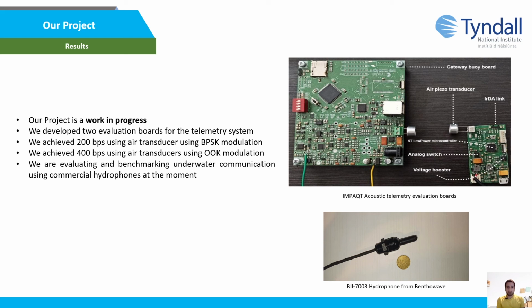So far, we were able to communicate at 200 bits per second using air transducers with binary phase shift keying modulation, and also we were able to achieve 400 bits per second using on-off keying modulation. Shortly, we are going to test this system underwater, and we are expecting that we will see a huge performance increase since we are going to use 380 kilohertz piezo transducer materials.